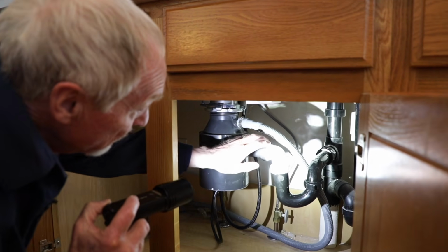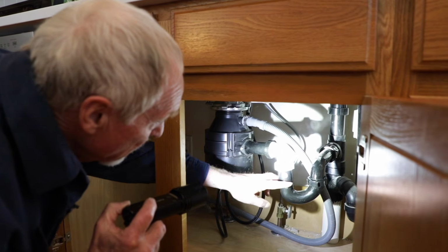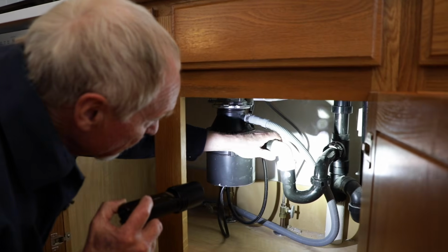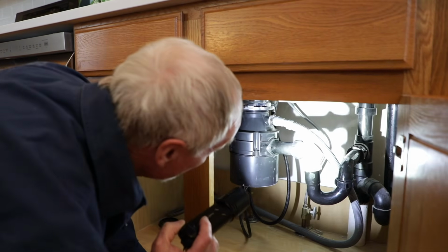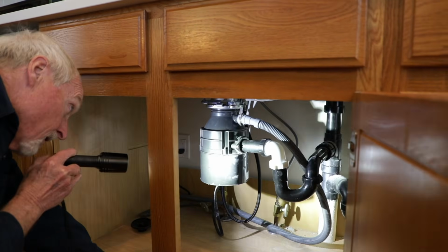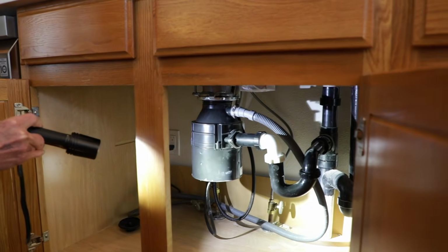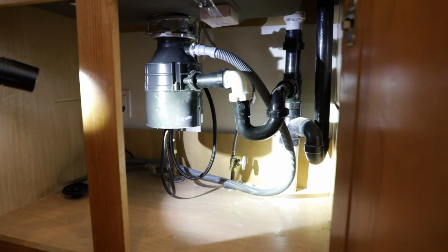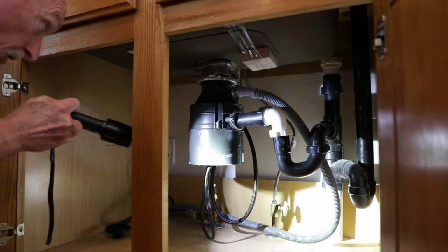And by the way, we can have a PVC elbow on our ABS other fixtures here because they're not glued together. They're just strictly screwed together here with the couplers, and that is okay. So we're looking okay. And by the way, that is not PVC pipe down there at the bottom glued to ABS. Somebody textured and painted the ABS, so we do not have an issue there with the way that is put together.